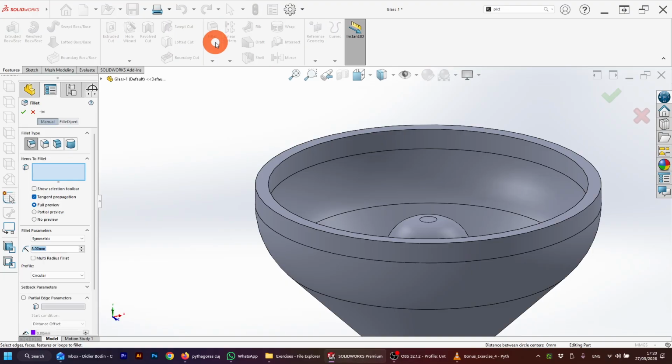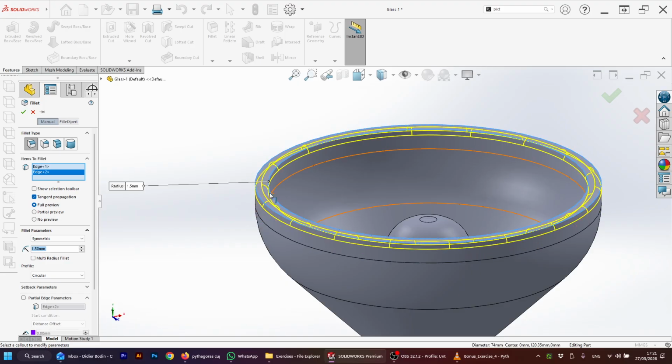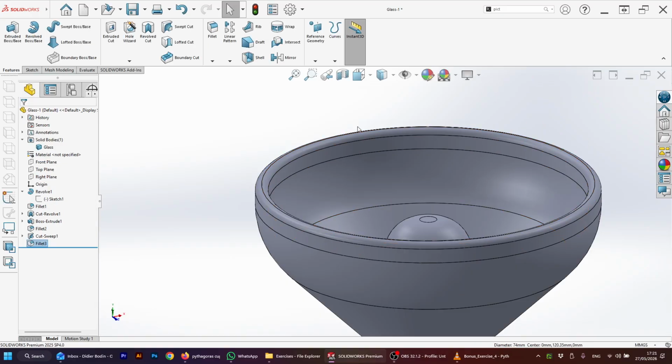It's here in the middle. The fillet is what makes edges softer. I'm telling it that the fillet will be 1.5 because I remember that I put the thickness of my plastic being 3. Since a fillet is trying to make a perfect half circle or quarter circle on the edge, it cannot be bigger than the thickness of plastic that I have. So that's why if the total plastic is 3 and I want to have round in and out, 1.5 multiplied by 2, 3. Therefore, I have the shape.